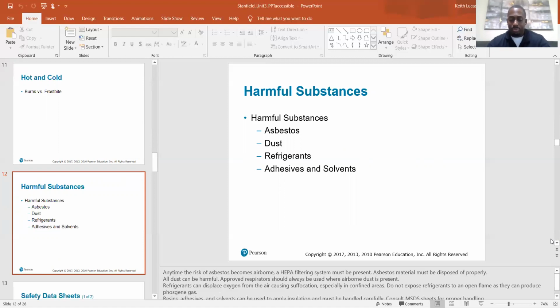We'll go over it a little deeper in this module, but on your hoses there's a check valve. Once that valve is released and closes, the refrigerant will stop flowing. So you've got to hurry up and finish taking it off or finish putting it on, whichever you're doing. If in doubt, just close it again. If you open something and things don't seem right, or if you weren't ready, just close it again. Don't just freeze up. I've seen that happen very often, and it's not a good method. So be safe and be sure about what you're doing before you do it.